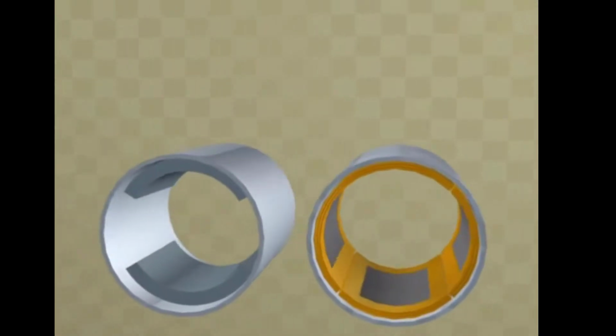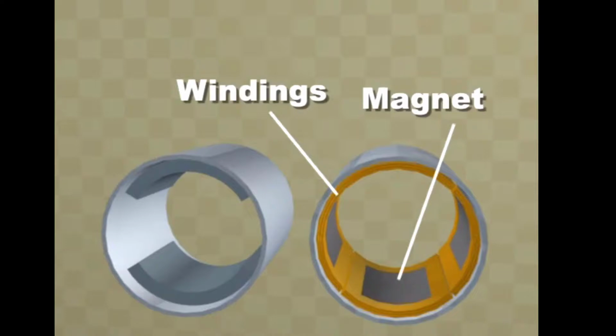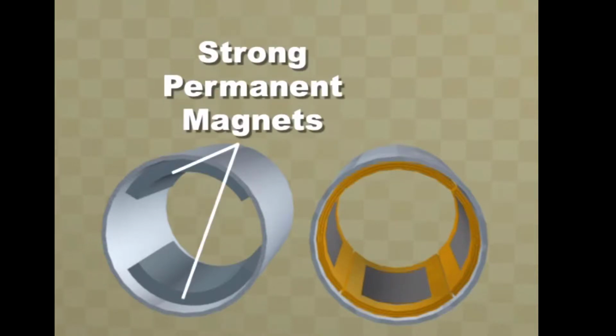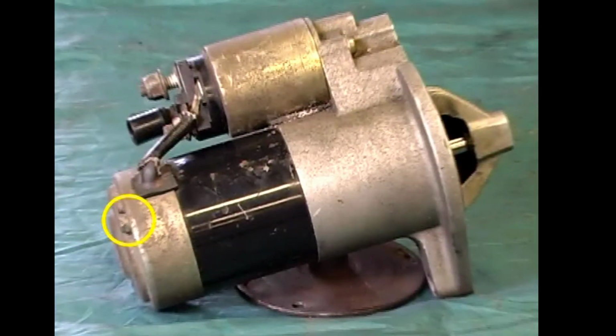In the past, most starter motors used heavy-gauge field coils mounted around iron pole shoes. The magnet and windings produced a stationary field. Now, the trend is to use high-power permanent magnets only without the field windings. This reduces motor size, weight, cost, and complexity. Long bolts feed through the brush end frame, center frame, and thread into the drive end frame to hold the starter motor together. By removing these two bolts, you can disassemble the starter.